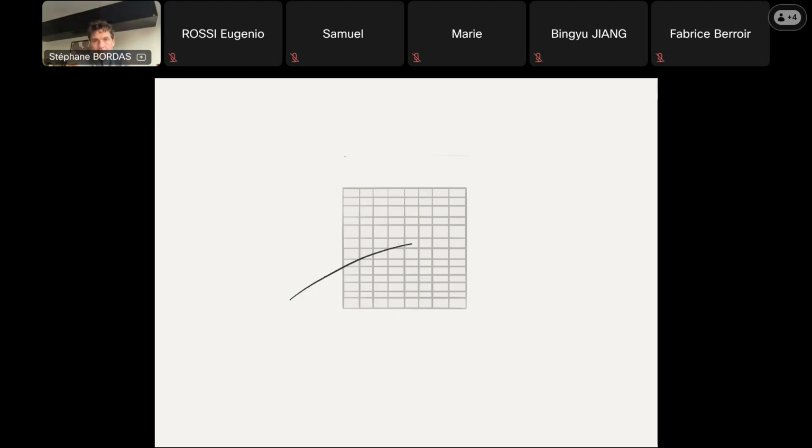So I'm now going to tell you what happens if you do that enrichment out of the box. So let's say that you have a crack and you have a mesh. The crack tip is here. You look for the elements to enrich. So we look for all the nodes such that their support contains the crack tip. What is the first one? That one. That node, the bluish thing, contains the crack tip. And that guy here contains also the crack tip, right?